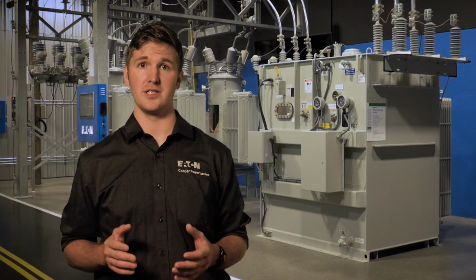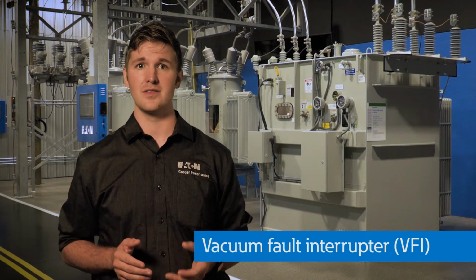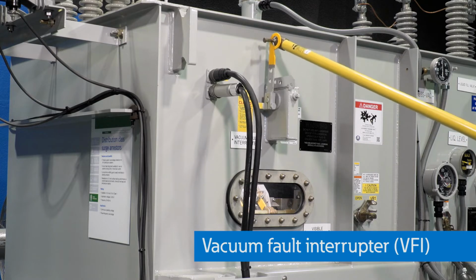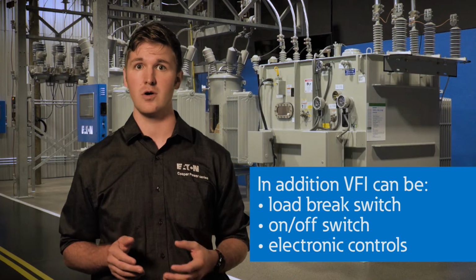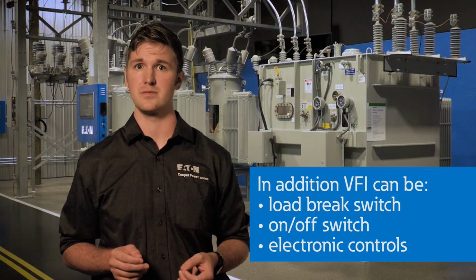A type of breaker that is unique to Eaton transformers is the vacuum fault interrupter, or VFI. This device is integrated directly into the transformer as an electronically tripped and resettable primary protection device. In addition to the protection, this device can also be used as a load break switch or on-off switch, and has electronic controls to allow for external control schemes.